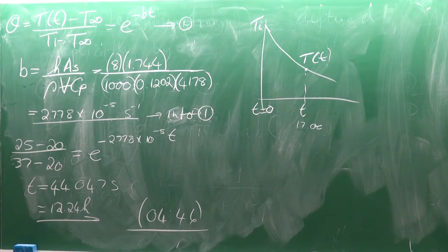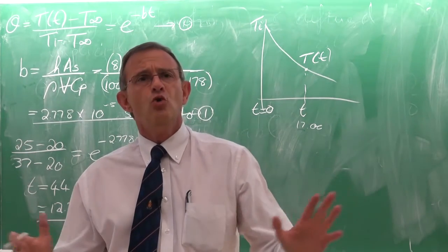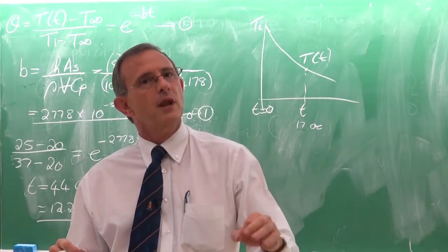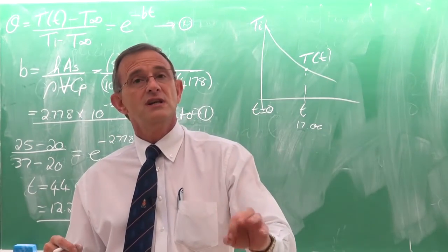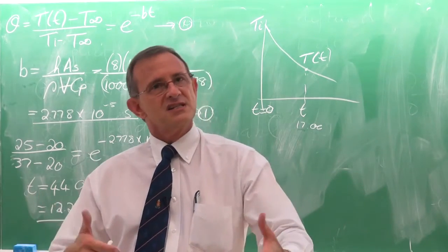Sorry, sir. You said the lump sum approach wasn't supposed to be used. Yes, because the value was small. We used it anyway. So is that value correct now, or do we need to do another approach? Remember, what I've tried to show you with the Biot approach is there's absolutely no law in the world telling you the Biot number must be 0.1. It is always an engineering discretion of that ratio of the resistance.